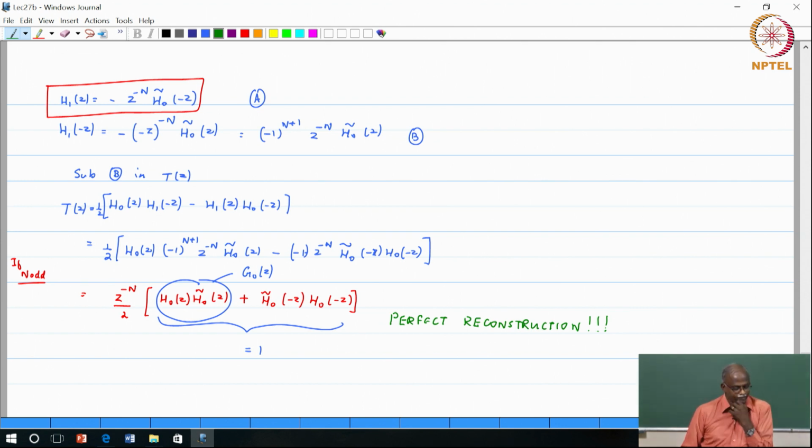That is perfect reconstruction. Okay? But maybe there is a little nagging doubt, well, you assumed n is odd, right? I mean, that is arbitrary. What did we say? G naught has to be a half band filter. What is the order of a half band filter? It is even but not multiple of 4. If I do spectral factorization, what will it give me? It will give me an odd filter, odd order filter. So, everything hangs together, there is nothing which is fishy about this thing.